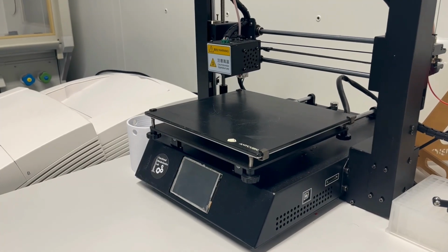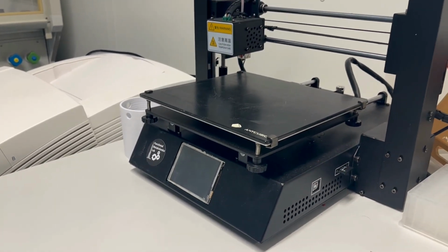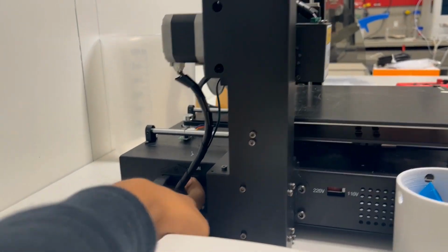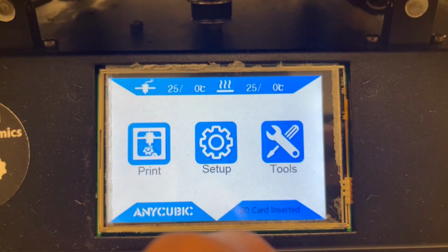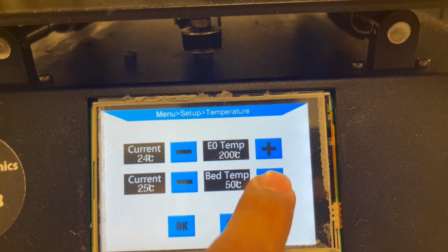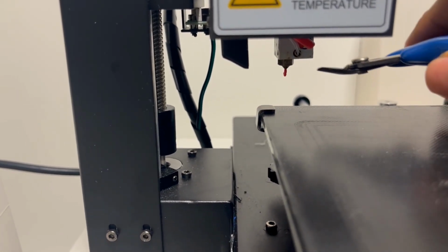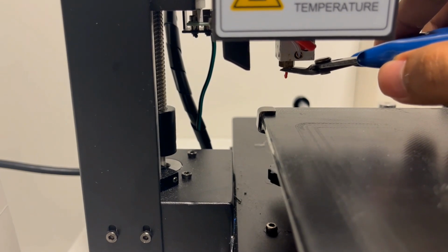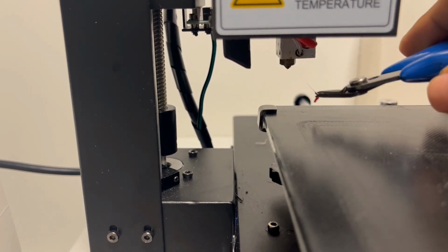With the file loaded onto our SD card, we can now begin the final step, which is setting up the 3D printer. After turning on and checking that the filament is running through the printer, preset the temperature settings of the extruder and the build plate to the program temperatures you selected. Let it warm up for a few minutes and clean the nozzle as needed, but be careful as the nozzle is very hot. Also, please do not use your bare hands to touch the build plate.